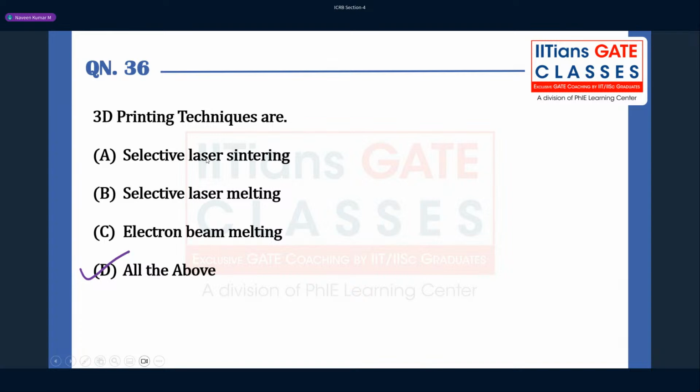Selective laser sintering is nothing but you have some kind of powder materials placed onto the bed, and then you put a laser on a certain path, and where you put the laser, the powder particles will be melted and fused together, and thus bonding occurs. Through that you can build layer by layer and get to the final part. That is one of the methods.